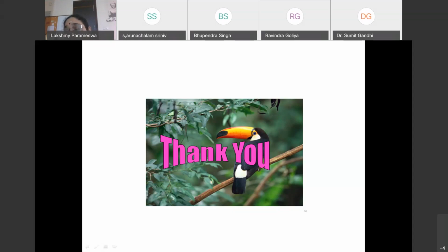And as I told you, the IRC SP 114 has given some special investigations which are required for bridges in seismic zones 3, 4, and 5, especially 4 and 5. If it is very close to the fault, then site-specific spectra, etc., are to be obtained.